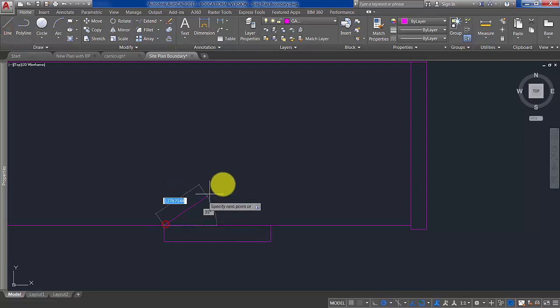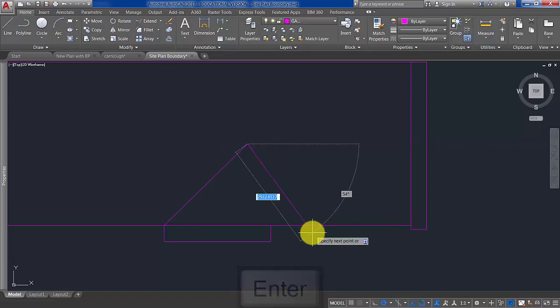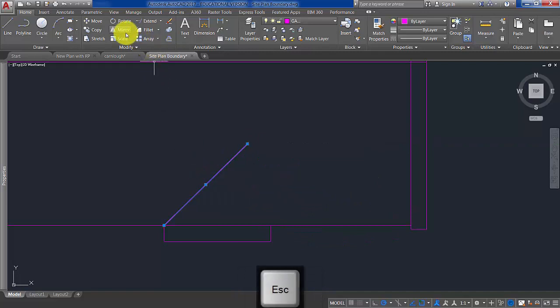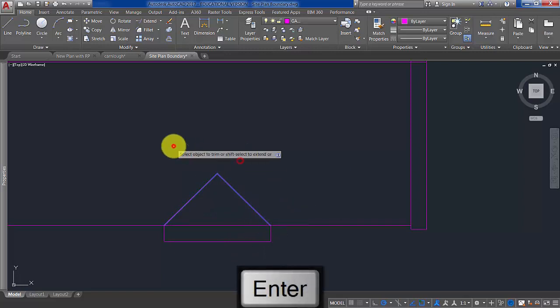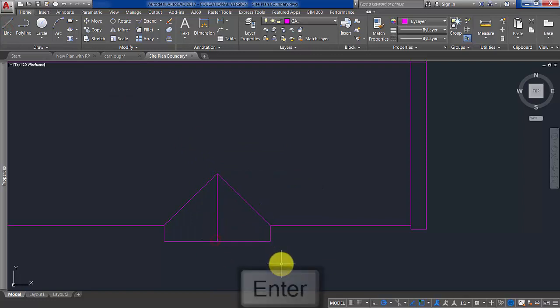Now where this porch part meets the roof there will be a valley, so that needs to be at an angle of 45 degrees. Hit tab, type in 45 degrees. Okay, and then if we mirror that, it will allow us to see where that part of the roof is. Again, I'm just using TR there, and we can take out that part and then add in a line for the ridge.